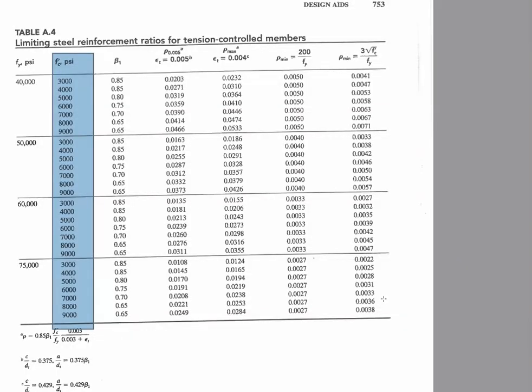So you start to have some movements in the building and you understand that, hey, there's some trouble here, time to evacuate, and you have a warning system kind of built in to your structure with that. And that would be the primary reason for having low strength concrete in footings, relatively low strength.